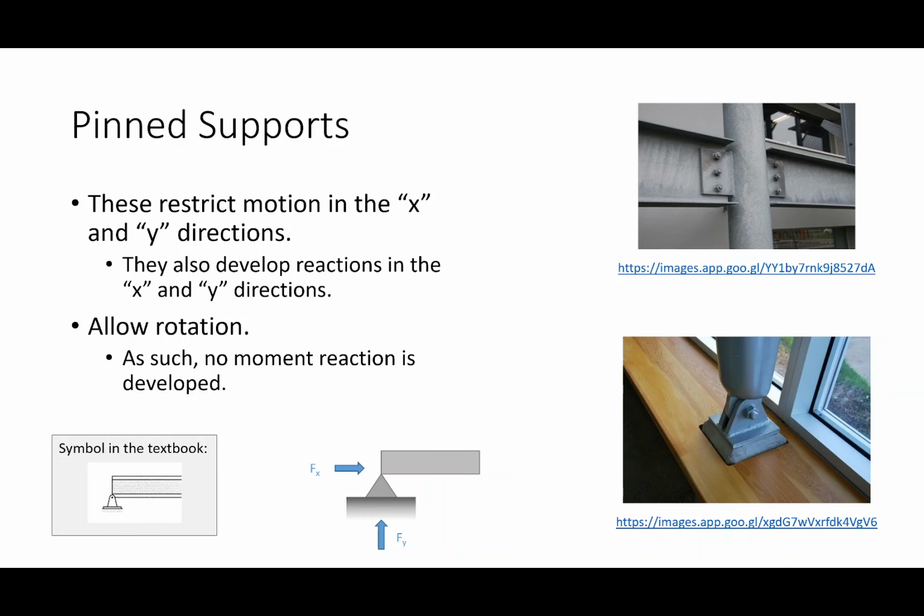I propose that pin boundary conditions are boundary conditions that prevent translation but freely allow rotation, okay? In other words, if I was looking at this boundary condition here on the bottom, that boundary condition would easily rotate. Like I could easily take this element and spin it about this little bolt, but I couldn't pick it up and move it up and down or left to right.